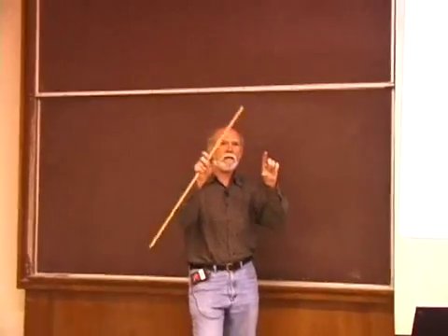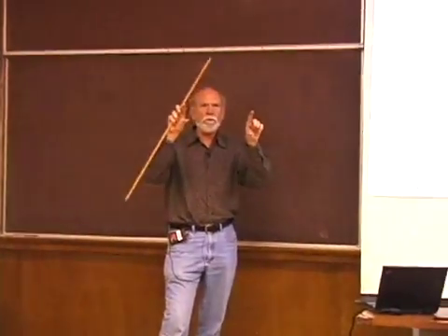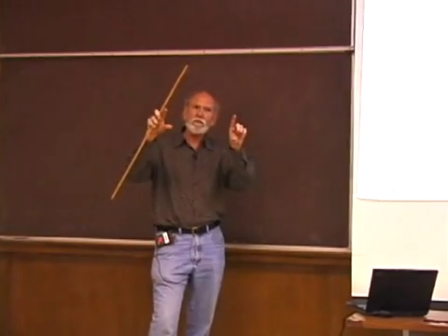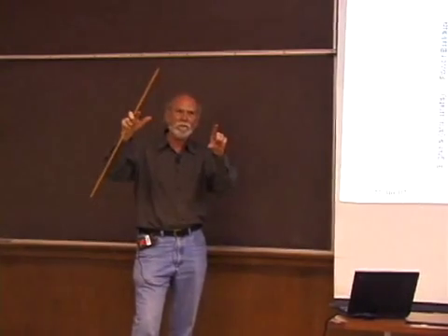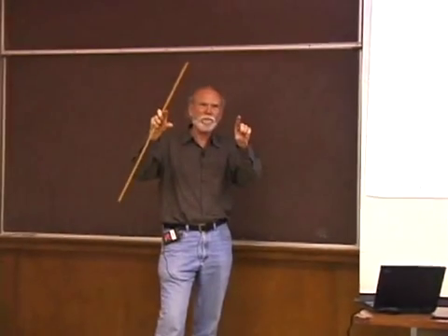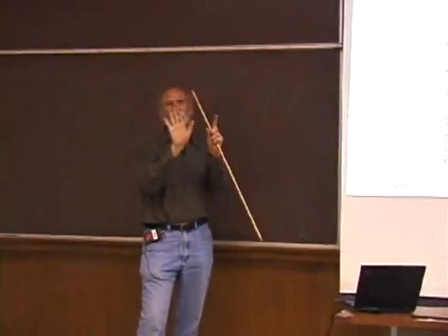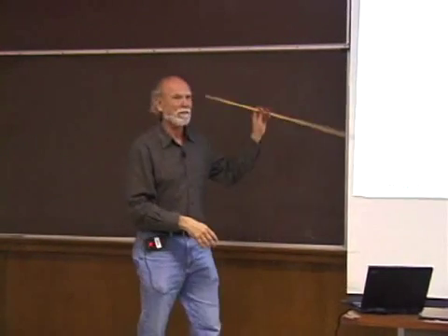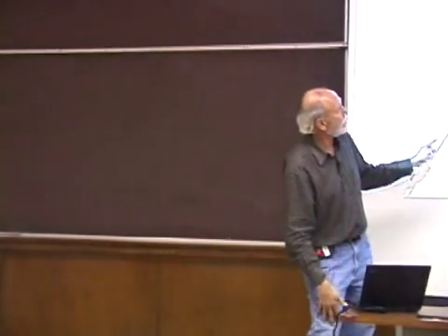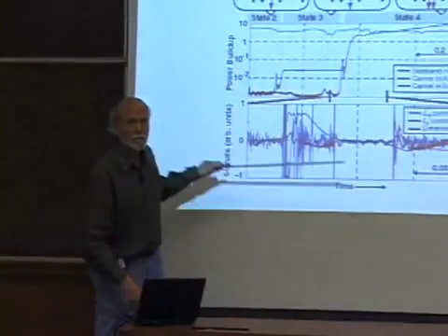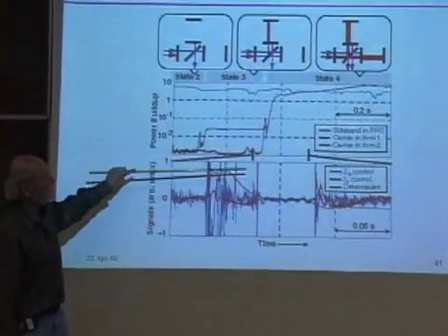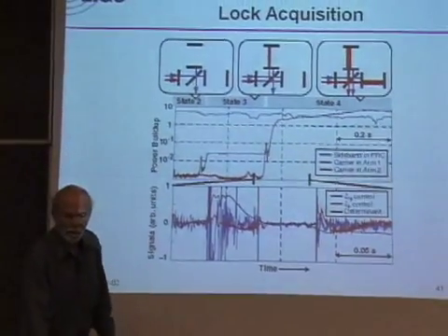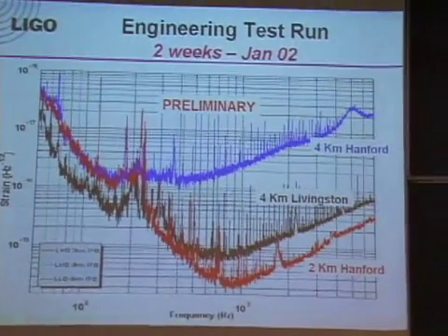And all these mirrors have on them 4 actuators. And you can imagine when things become nonlinear, they don't each saturate exactly the same. One of the little magnets saturates before another one, and so then it kind of goes out of lock in some funny way. So that's the kind of thing that does this. But it's a very hard job to get this completely to lock because it's a very large dynamic range and it's also nonlinear. So it's a control system with both nonlinearities and a very large range.